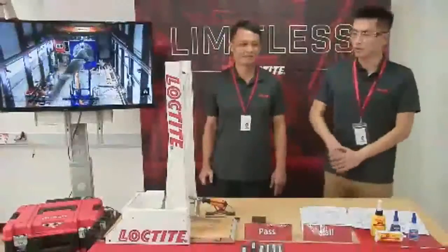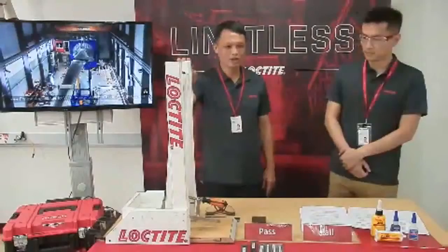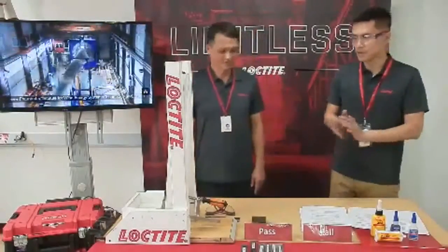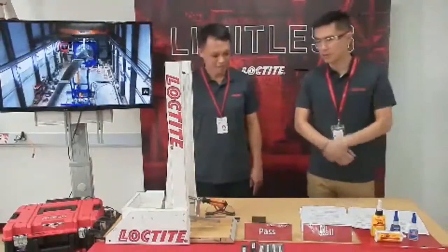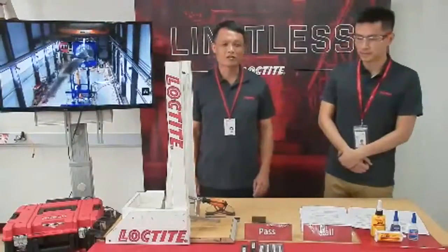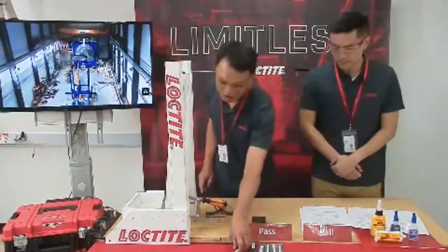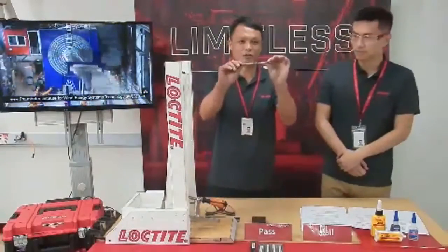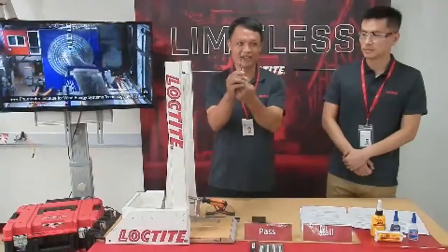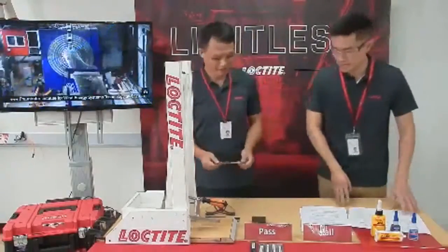Okay, so we're using this one today, right? Yes, we are going to use the jig to test the impact loading of the specimens prepared today. Good. So let's proceed to the most exciting part. Then when you do the test, how can we tell if it survived or not? The criteria to decide whether it's a pass or fail today is very simple. As long as the assembly breaks apart into 2 pieces, we will define it as a fail. If it's still intact together, we will regard it as a pass. Okay, good. That's simple.